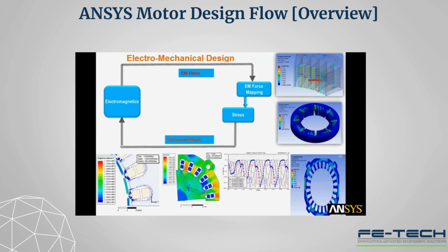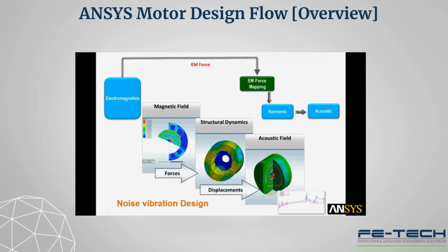The next step is electromechanical design. In this case, we map the electromechanically induced forces to a finite element stress analysis in Ansys Mechanical. Again, automated procedures in Ansys Workbench streamline the process. The mechanical stresses deform the geometry, and the deformed mesh information can be passed back to Maxwell for further electromagnetic simulation. For the final analysis, we pass transient electromagnetically induced forces to structural dynamics simulation in Mechanical to compute structural harmonics. Those harmonics change the shape of the stator, which in turn produces an acoustic field as computed by Ansys Mechanical. As you can see, this approach can be used to predict acoustic noise and hence enables you to apply strategies to reduce that noise.